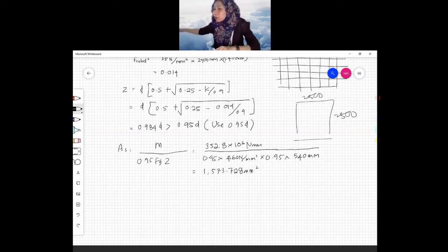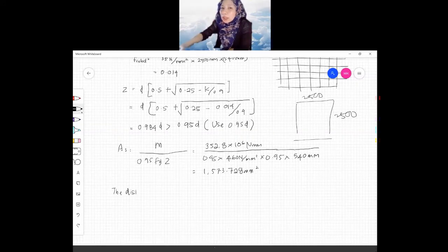Whether we need to concentrate the reinforcement at some areas or it's going to be uniformly distributed throughout the slab, throughout the foundation. Distribution of reinforcement. Because if you choose early and suddenly you have to concentrate at some areas, it makes life difficult because you have to find again. So, we check first.